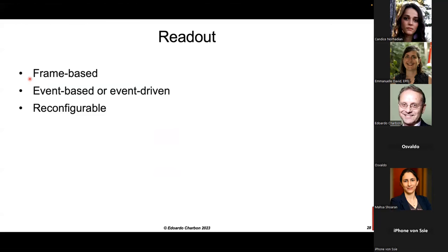One of them is known as frame-based, where basically everything is exposed for a certain amount of time and read out all at once. But one could think of having an event-based or event-driven approach, where as long as there are no photons, there's nothing being read out, but then photons will drive the readout themselves. Or you could think of a reconfigurable device. And I'm going to give you an example of a reconfigurable device.